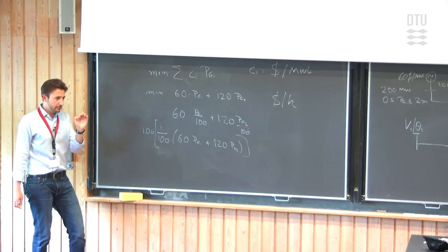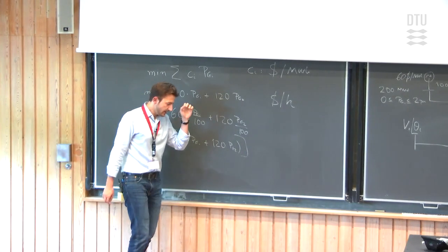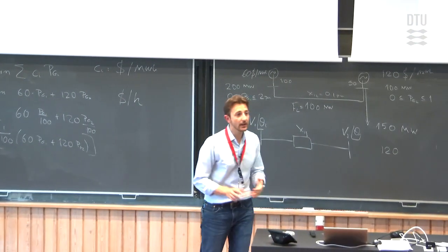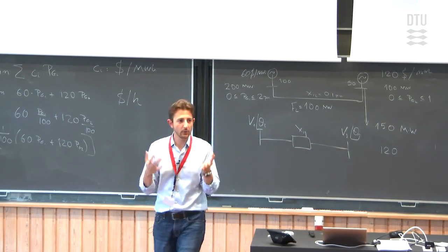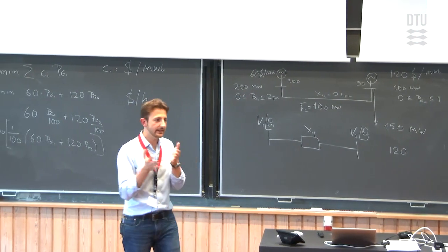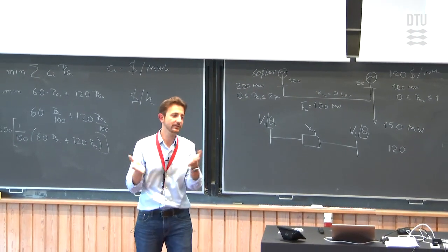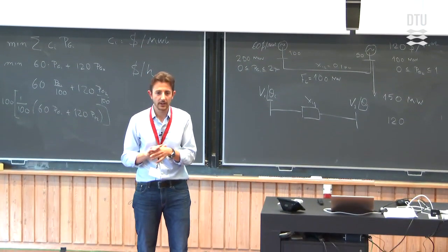Now, I'm going back a little bit to the optimization solver before we get the break. If you go into the parameters of your optimization solvers, you're going to see that there are tolerances, okay? Because after all, these solvers work numerically, and they try to converge the solution. And if the tolerance is below a certain value, for example, for the objective function, then they say I have found the optimal solution, okay?